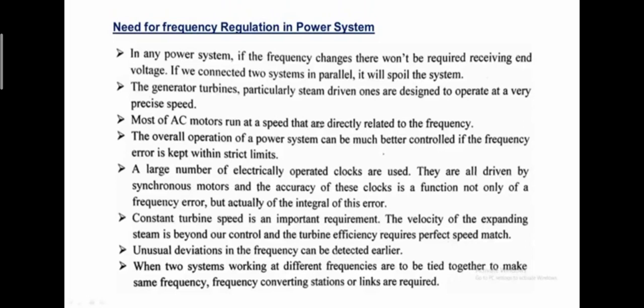The rotating magnetic field rotates at synchronous speed. Here, if the frequency value decreases, the rotating magnetic field speed decreases, and as a result the rotor speed also decreases. Overall operation of the power system is much better if the frequency error is kept within strict limits.